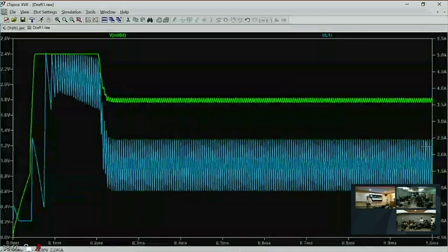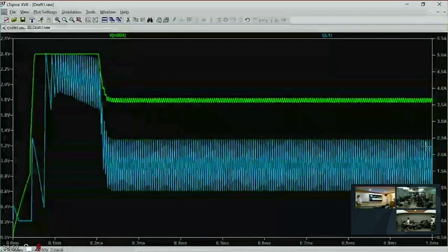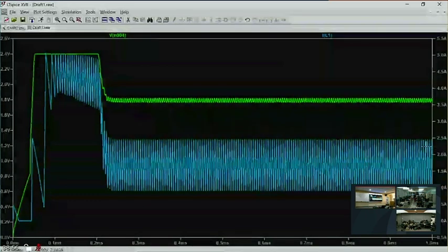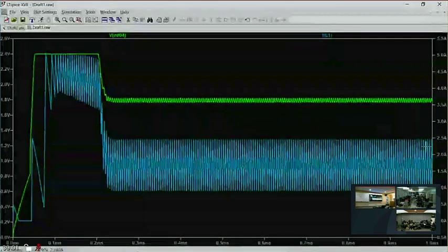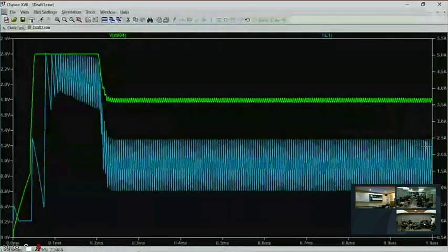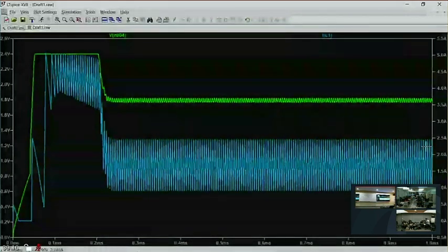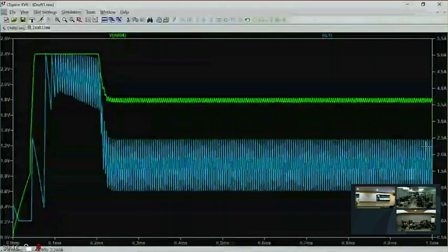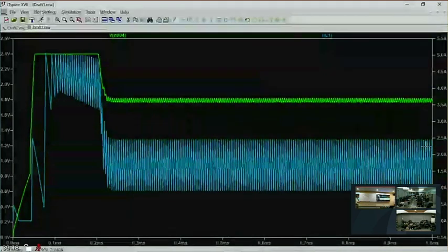Now, what is slope compensation? Slope compensation is a fix to a grave problem in peak current mode control. See, the whole premise of this is that if I drive this flip-flop and operate it like this, since this voltage is controlling the peak current, and since the average current is related to the peak current, it means that voltage is controlling the current. That's the premise behind current mode control. And why that's important is something I'll get into in about 25 minutes.